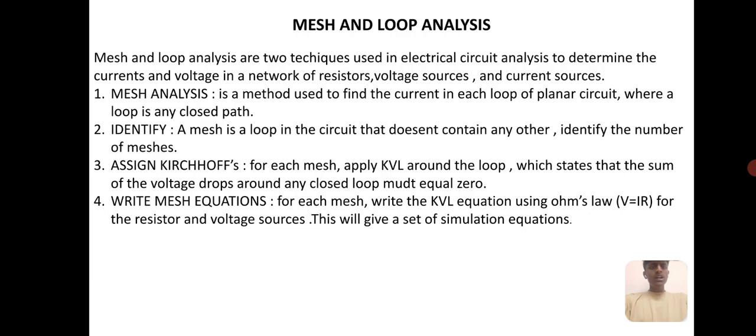Now write the mesh equation. Mesh equation is easy. For each mesh, write the KVL equation using Ohm's law. Ohm's law is very important, which we have studied in earlier classes. So V is equal to IR for the resistances and voltage sources. This will give a set of simultaneous equations.